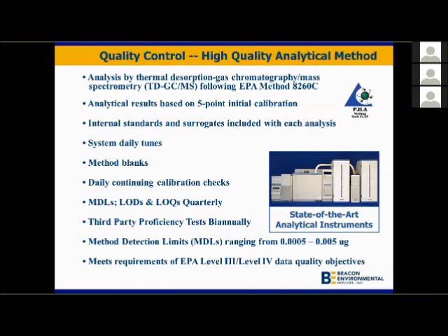Now, the data reported with a passive soil gas survey is in units of mass of individual compounds that are absorbed throughout the exposure period. Federal and state regulators are not accepting passive soil gas data converted to concentrations, but reporting the data in units of mass still meets the objectives of a passive soil gas survey, which is to collect high-resolution data to effectively screen the site in order to focus where soil and groundwater samples should be collected, to identify whether a vapor intrusion risk might be present, tracking groundwater plumes, and focusing remediation efforts. That is to make sure that you are injecting or extracting in those areas where your efforts will be most effective.